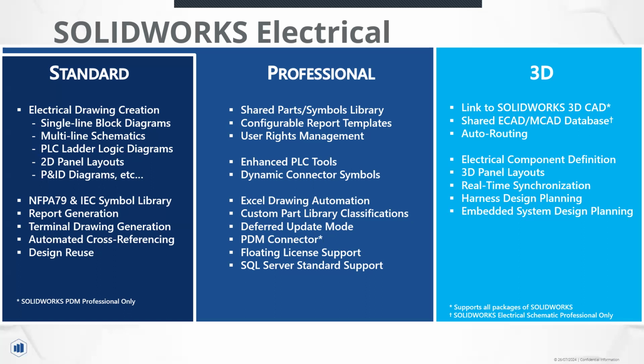That is a question that we do get a lot: what's the difference between electrical 3D and the routing capabilities in SOLIDWORKS Premium? The critical answer is that in electrical 3D, the schematics that you create are driving what is being routed. If you don't have an electrical schematic that's helping with your harnesses or your wire routing, you want to look at the routing in SOLIDWORKS Premium. That's the key difference there.